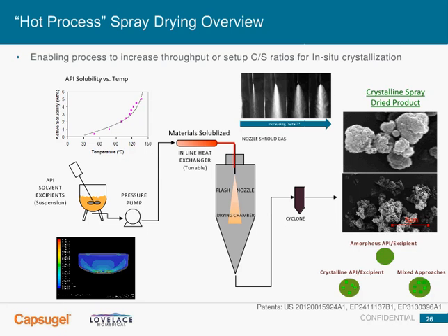One other approach, and certainly we use this for a lot of the brick dust compounds, the compounds that are basically insoluble in just about everything, is where we'll take a slurry of active and/or excipient, and under high pressure feed them to a heat exchanger just before the spray drying chamber, where it will heat up that solvent to superheated temperatures under pressure to prevent boiling.